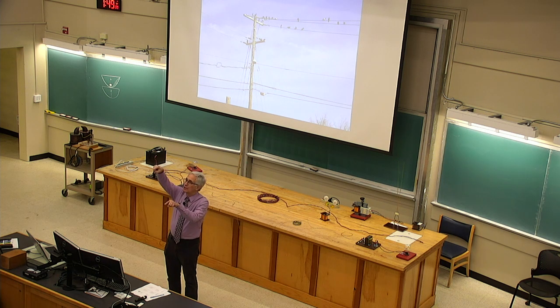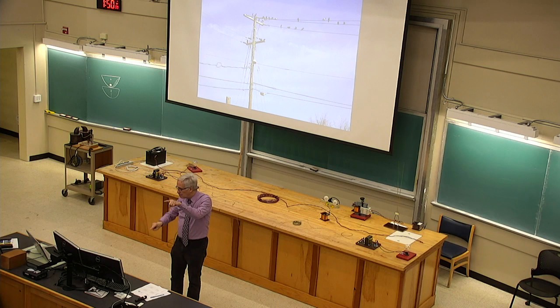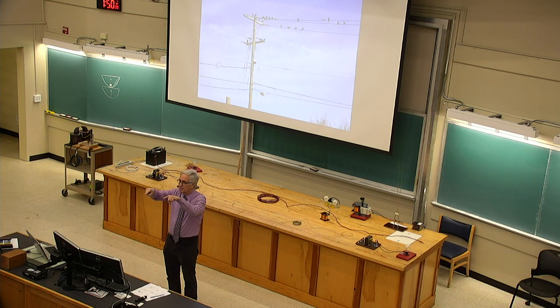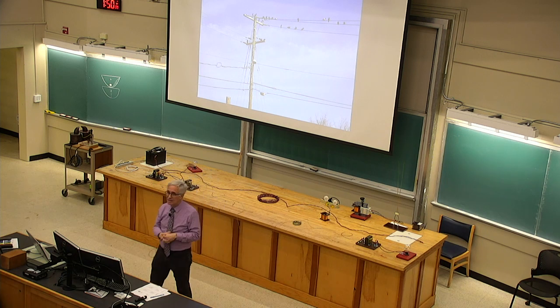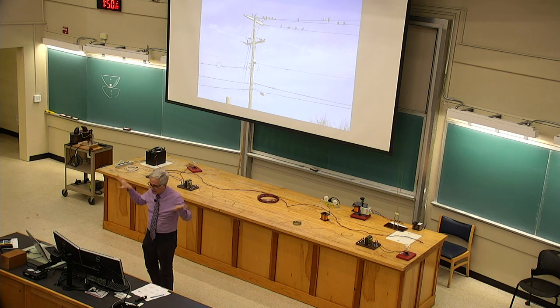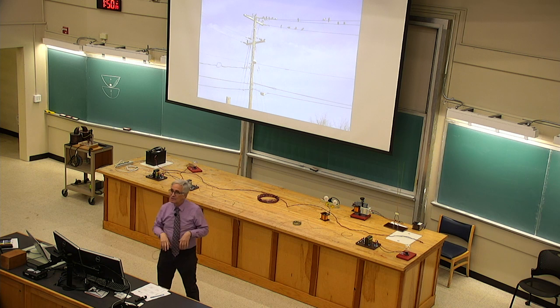It goes up in voltage relative to the ground for a quarter cycle, then back down, and then it goes below the voltage of the outside and back up for a quarter. So it's rising and falling, and it's actually rising and falling more than 120 volts. Why? Because the 120 volts that normal electric power nominally has is at an average-ish voltage.